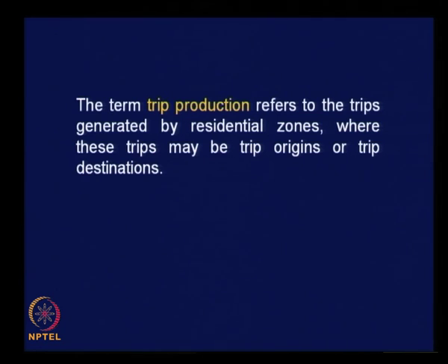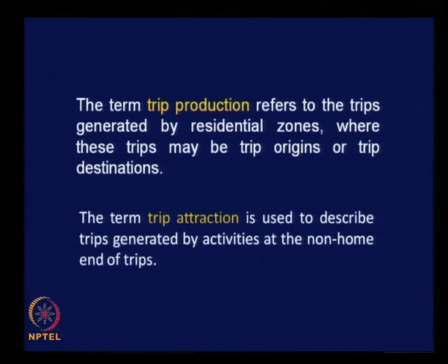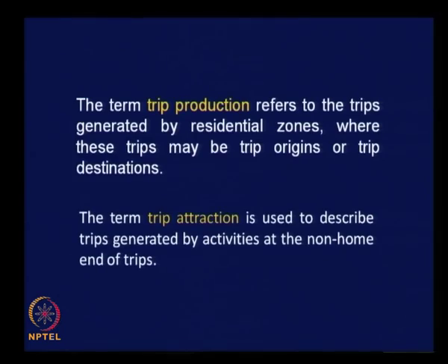Then obviously, trip attraction means trip ends that are neither the starting point nor the end point associated with home. They have some other origin and a different destination. This term is used to describe trips generated by activities at the non-home end of trips. Non-home ends could be workplace to shopping area, to workplace, or one workplace to another workplace. All these movements are trip attractions.